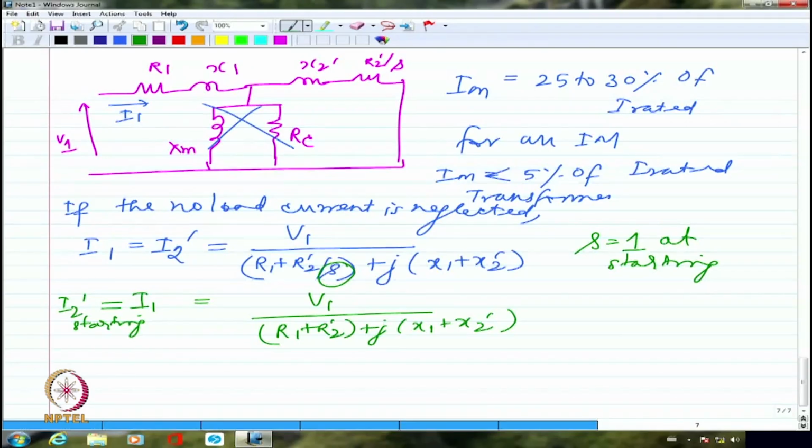I told you that induction motors are at very high ratings also. If it is an 850 kilowatt induction motor working at 11 kV or 1.1 kV or whatever, you can calculate what the rated current is. It will be root 3, 1.1 kV, maybe I am going to have 0.8 as the power factor at the most.